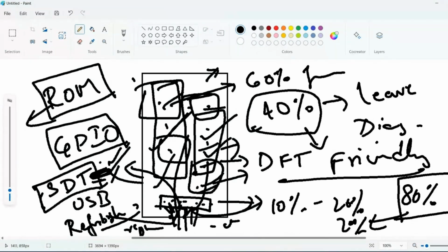You will only know what to replace when the diagnostic tool is run and it says passing or failing. That's how you can identify it. The diagnostic tool will have your golden patterns. Previously, I told you DFT will give you the final post silicon patterns proving that my design is 90% or 100% testable, fault free. Those patterns are fed into this diagnostic tool.